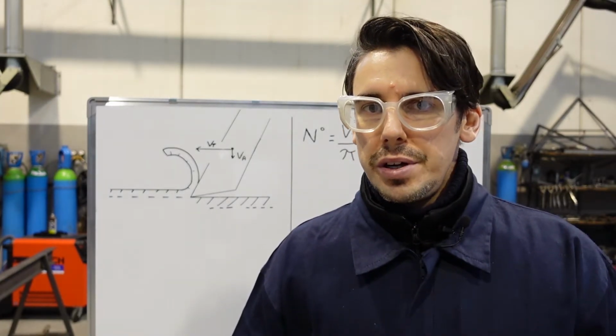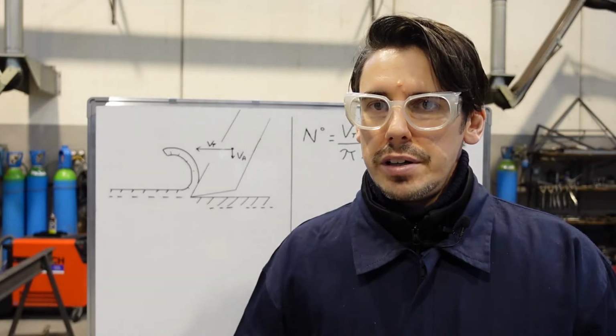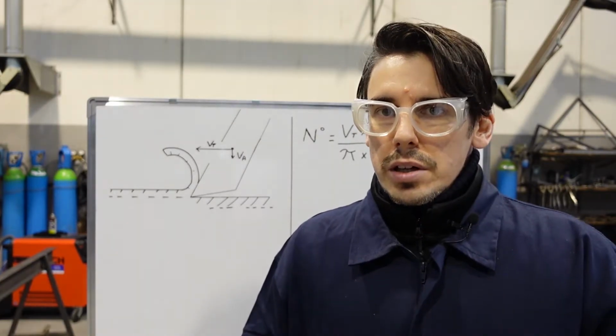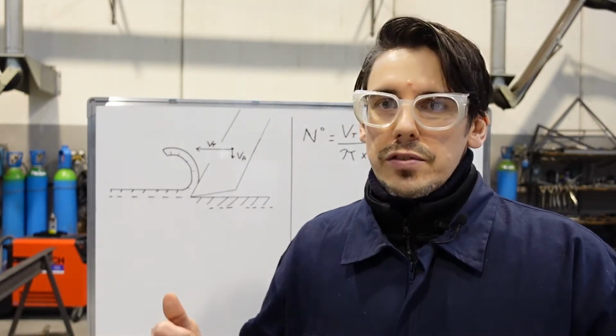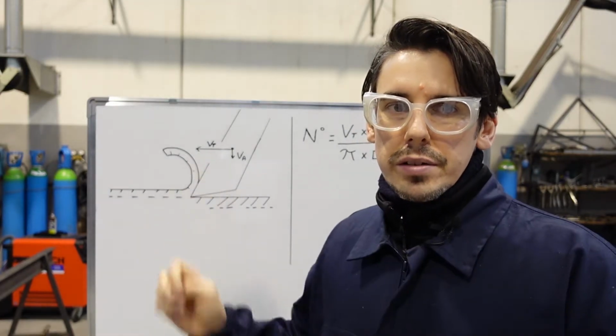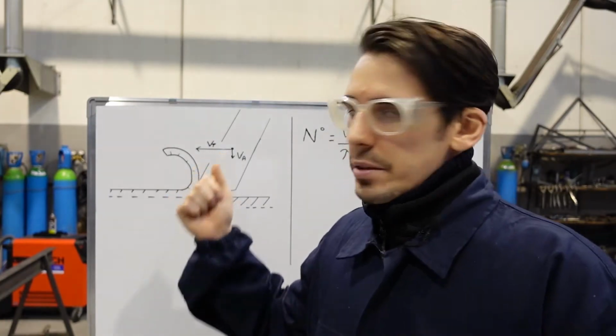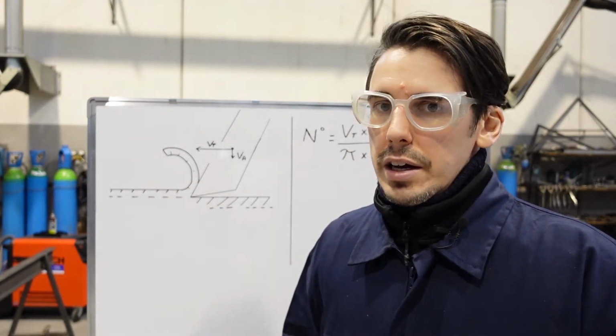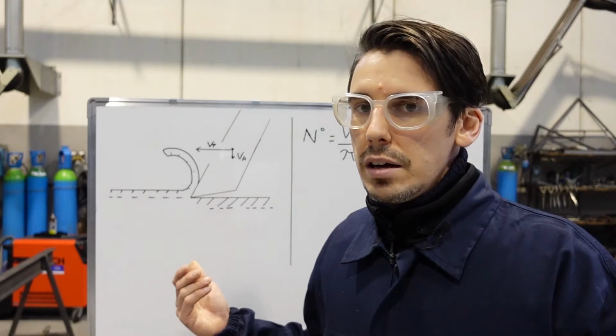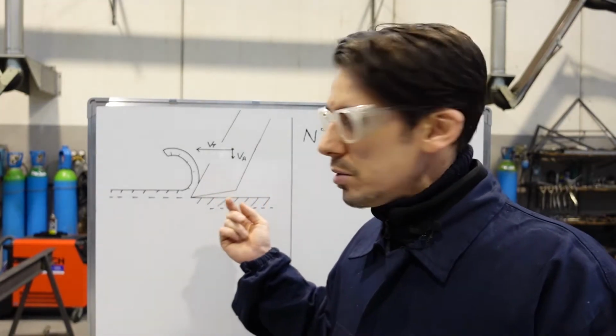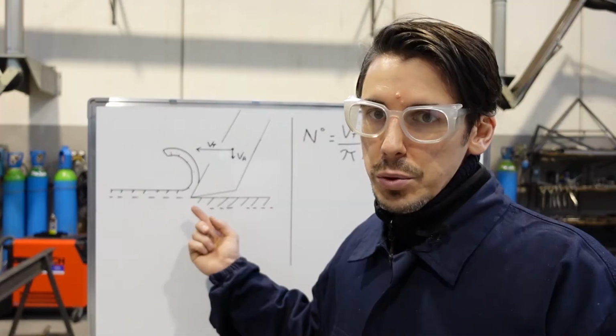But before showing how to transform this theoretical number, I have to add something. There's another speed called advancement speed. Briefly, the cutting edge moves in two directions. One is the cutting speed. The other is the advancement speed. This speed allows the tool to find other material that will be removed.